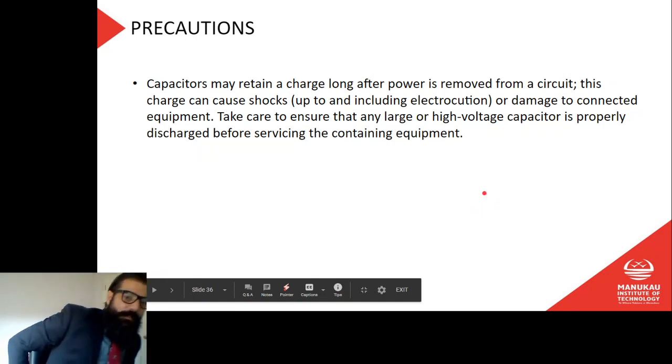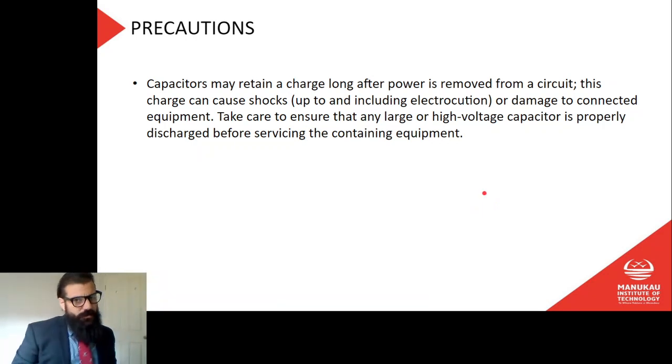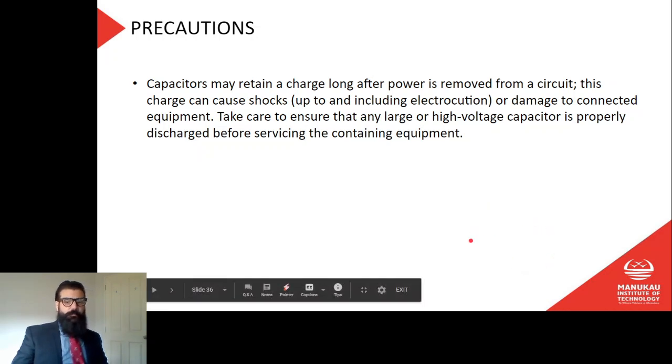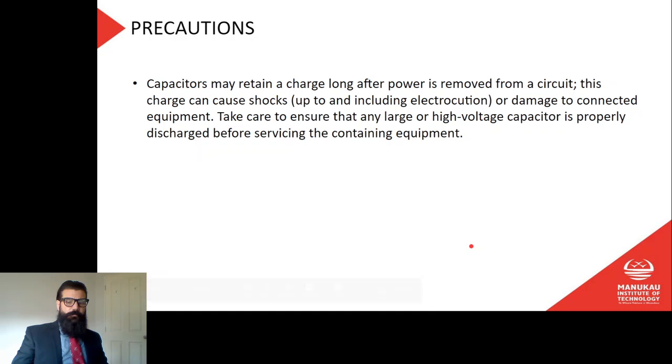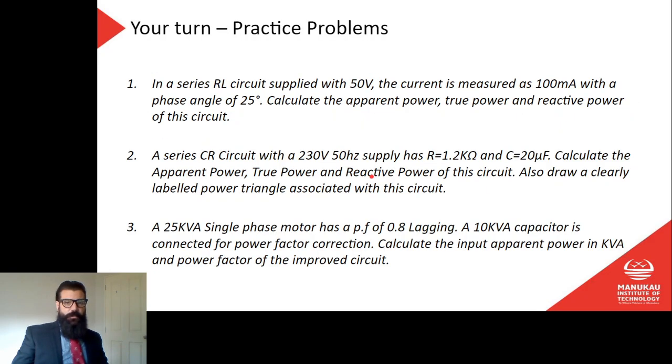Precautions. Capacitors may retain a charge long after power is removed from the circuit. This charge can cause shocks, up to and including electrocution or damage to connected equipment. Take care to ensure that any large or high voltage capacitor is properly discharged before servicing the containing equipment. Yeah, be careful with capacitors, team.